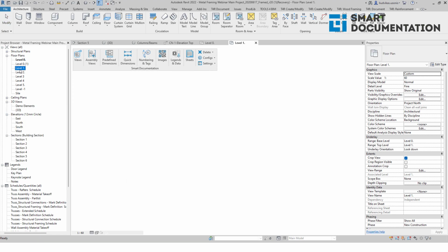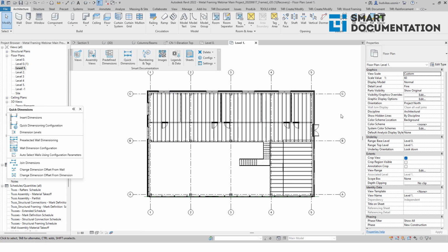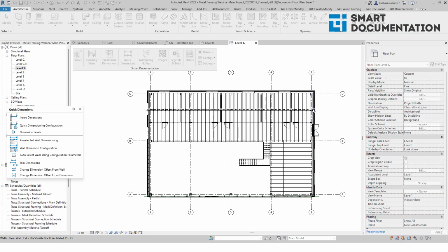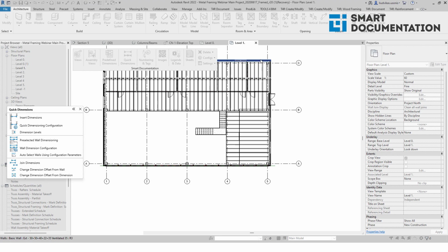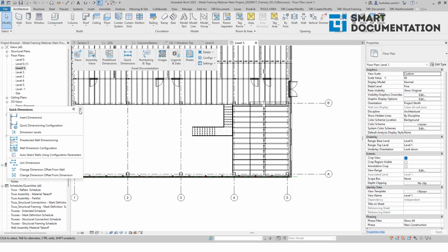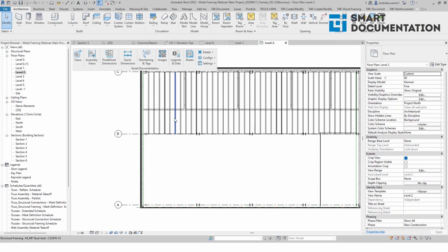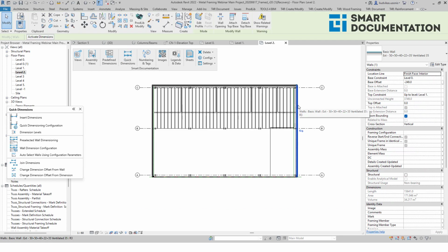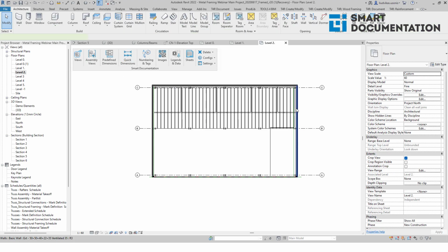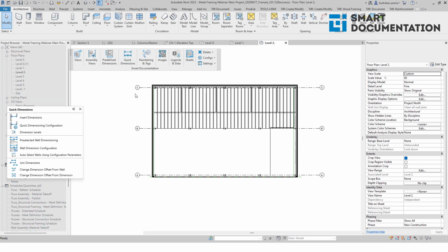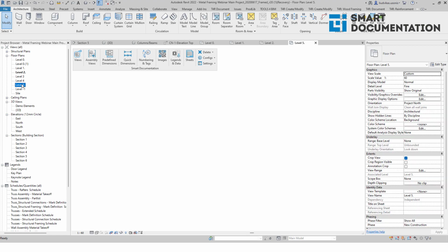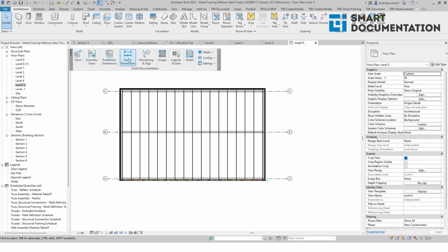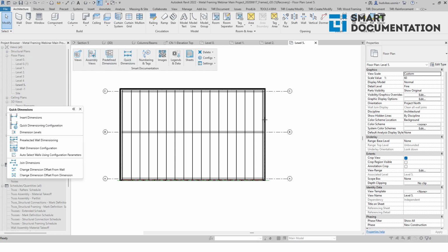Alright, we can jump into the next floor plan. Here I can do the same from this point to this point. Insert dimensions. Again, right, we have them. Now we have also joists right here. Very simple tool to use. We have another floor plan from here till here. So I think you get the principle how we can dimension these joists quickly. Maybe I'm pressing too fast. And at the top we have trusses. So we can dimension them as well using this tool.